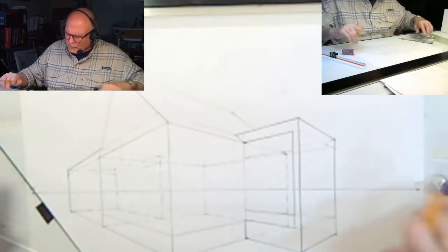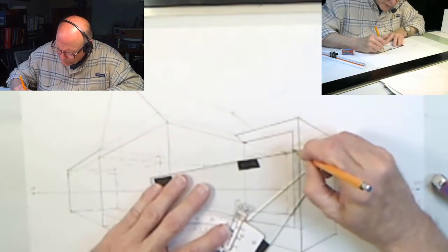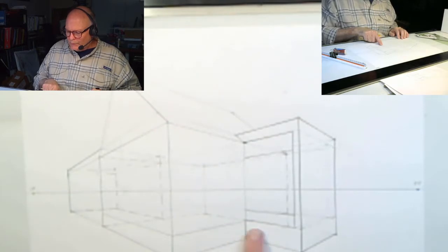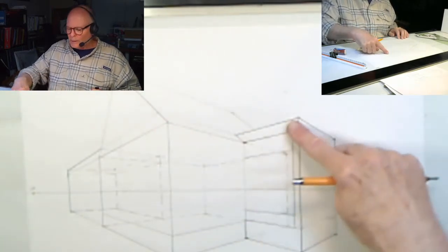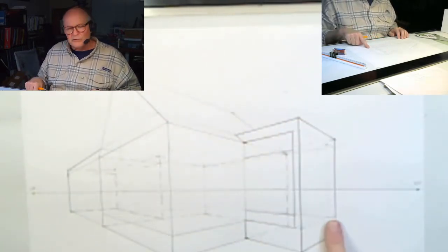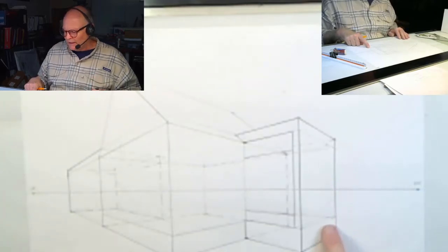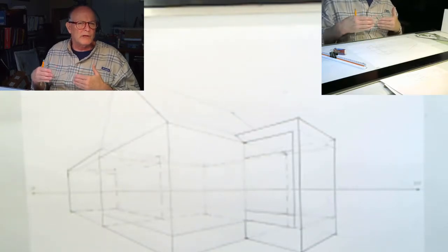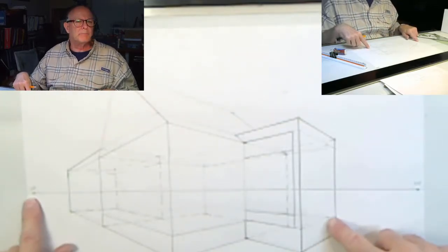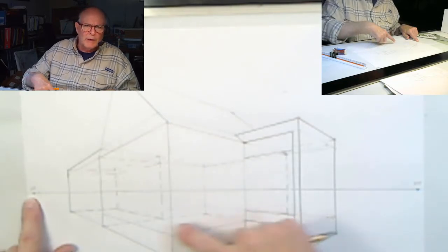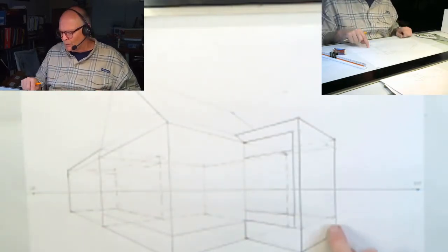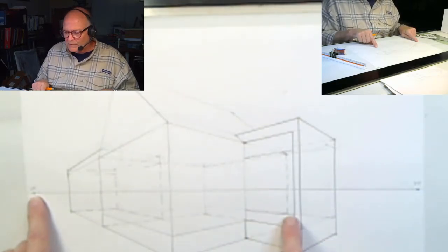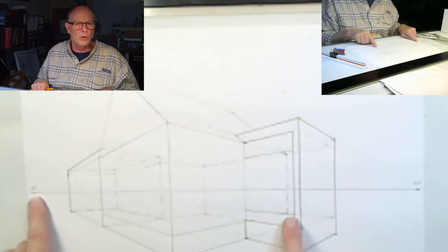Be careful with those phantom lines so you don't get in the way here. Okay, so we used the base, we used the top, we found the thickness. The thickness extended back, we gave ourselves about 1/8 of an inch as a thickness of the wall, just so that we represented some wall thickness, and projected it back to the left vanishing point by going through that 1/8 inch marker and extending it back. And that provides us with this lower interior wall.